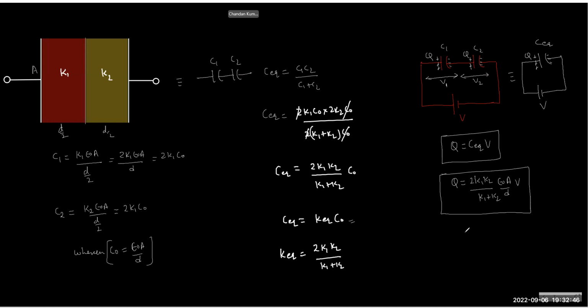So getting this answer, what else can you ask? Now see, because we got the answer, you may need to find the voltage of each plate. So the voltage of each plate we can write as Q by C1. In a way, it's very beneficial because you know Q, you know C1. Simply substitute, and we get the answer, isn't it? So how much is V1?